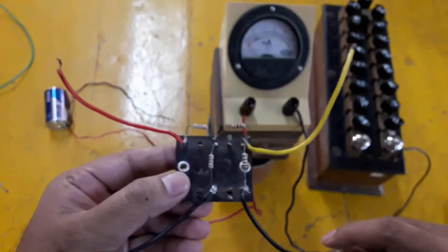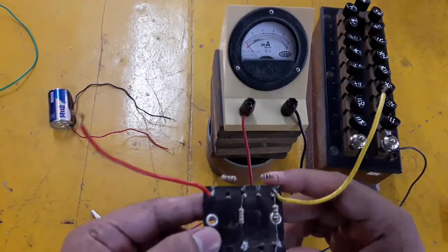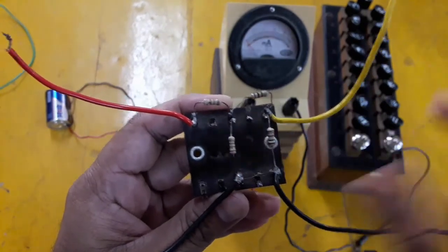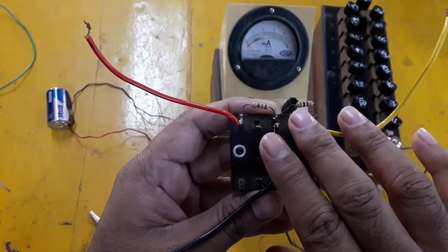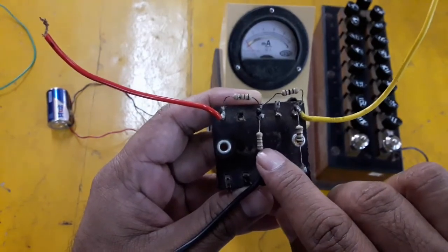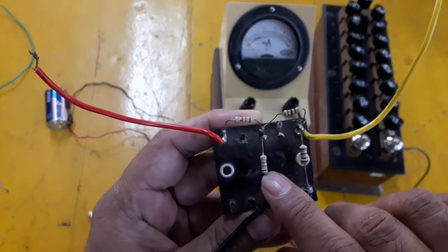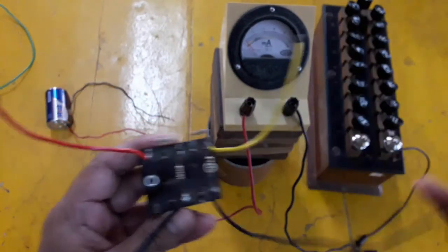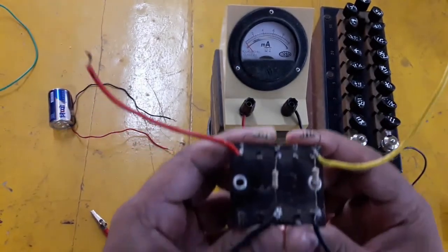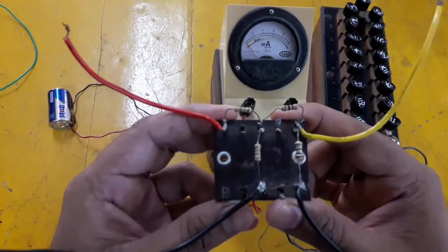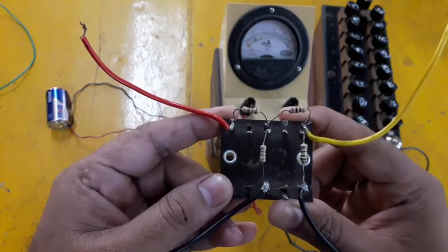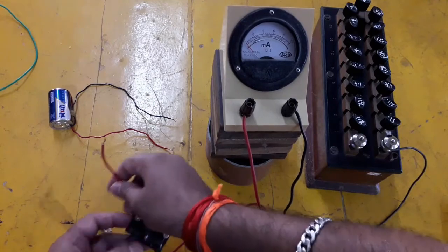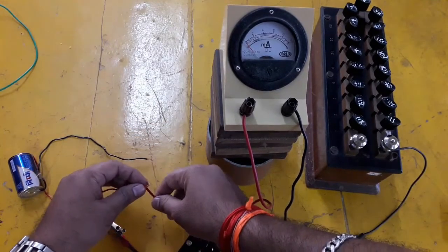We'll be using this circuit for the first part of this experiment, and to prove Thevenin's theorem, we will then change this with the equivalent of the resistance which we have already calculated. We have found the Thevenin resistance RTH is 75 ohms and VTH is 0.393 volts. We will have to replace this with the resistance box and a voltage source, which we will do in the second or third part of this experiment. Okay, so let's start the experiment. As you know, we have this circuit that's connected to the battery, red to the red.